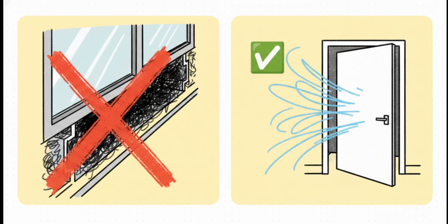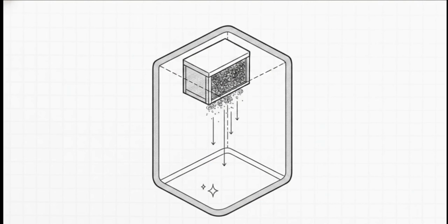Take doors, for example. In regular architecture, sliding doors are fantastic space savers. But in a pharmaceutical cleanroom, sliding doors are highly undesirable. Why? Because the tracks create these uncleanable little recesses where particles and bacteria can just hide out. Instead, guidelines mandate swing doors equipped with self-closers that open out to the high-pressure side. This makes sure the door is naturally kept shut by the room's air pressure, which maintains the integrity of the barrier. The physical armor of a cleanroom is designed to leave microscopic invaders with absolutely nowhere to hide.